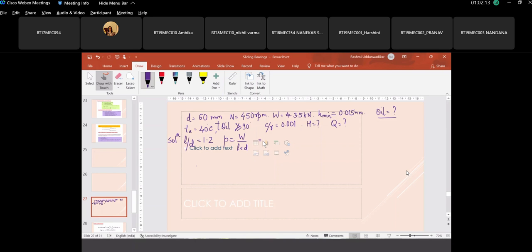It increases with more and more installations on the shaft. It's carrying a pulley, a sprocket, a gear. So the moment you pick up or design something heavier, the load increases. Okay, so this is 0.81 MPa.